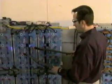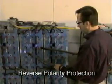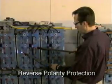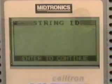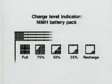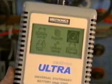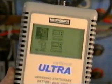To protect its circuitry, the Ultra will not turn on and display or sound a warning if the clamps or probes are connected in reverse, red to negative, black to positive. A small box in the upper left corner of the display shows the charge level of the analyzer's internal battery pack.